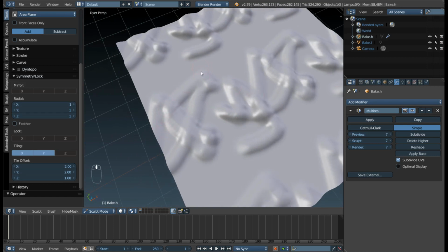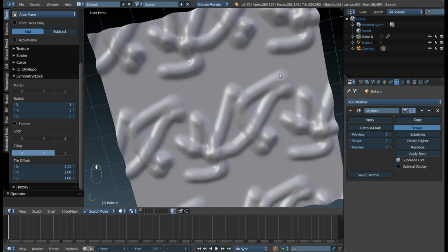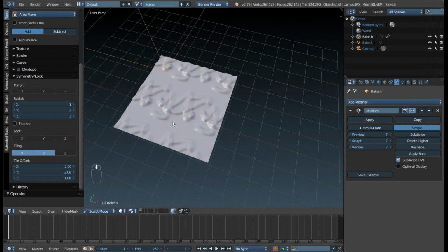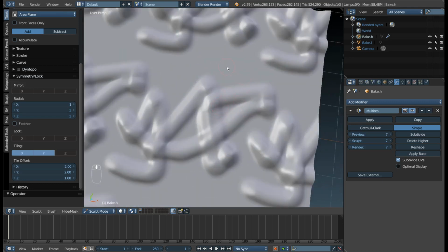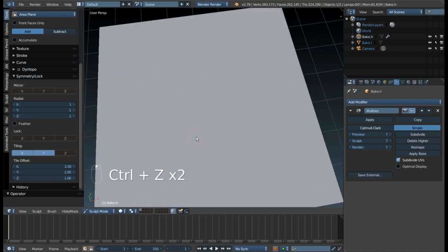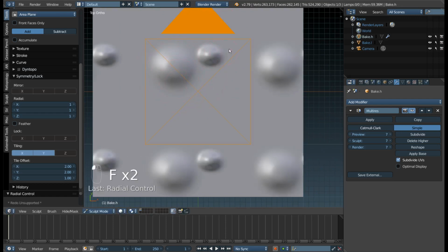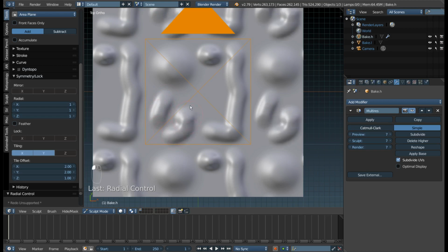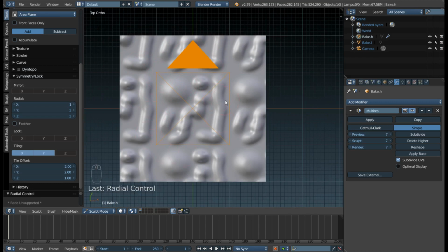the borders. If we had borders here, then we should worry about how they will look on the baked seamless normal map. Will they have seams or something like that? If we set the high poly sculpt like this, then we don't need to worry about crossing the borders. And actually this is what you want, to cross the borders and to break the repetition, because if you place your details inside of this square, although it will tile, it will also look artificial. You can clearly see, even here, the repetition, and this is not good.